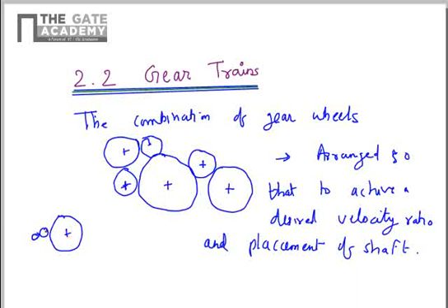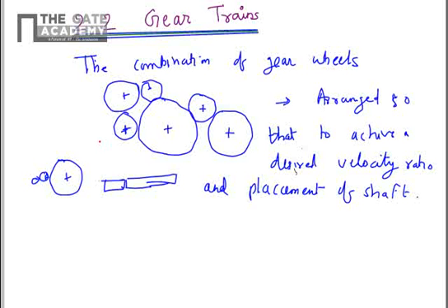If you want a simple system of two gear wheels in some specialized application, the design may come out such that the radius of one wheel is too high, or the tooth spacing is too much, or the load on the gear is so high that it is out of design limits. In that case, you have to break the problem into small parts and form a gear train. Our task is to determine the transmission of velocity from input to output. Let's say one of the gears in the gear train will be the input, and another gear will be the output. It can be any one according to the functions desired. First, we will consider the case of a simple gear train.